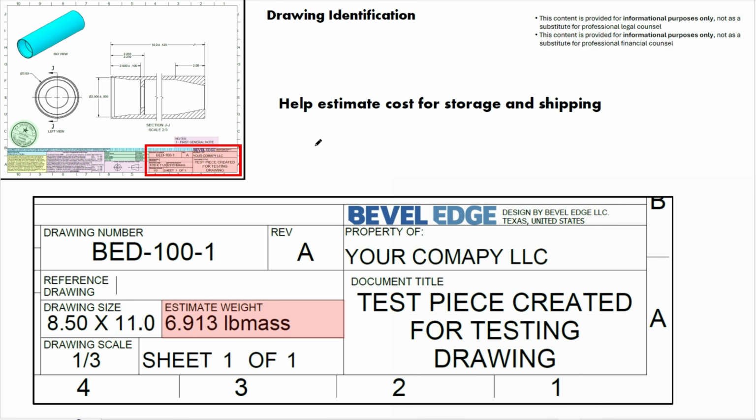All right. Next is the mass call out in the identification. So maybe you have the same part made out of gold, the same part made out of silver, or the same part made out of cardboard. Geometrically, in the drawing, they look the same. However, by having a mass call out, you can help distinguish between the two if that distinction isn't obvious to the manufacturer or the person reading the drawing right away.